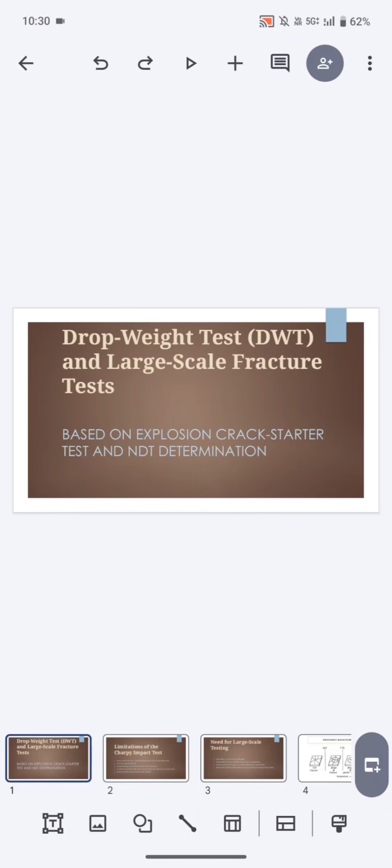The basic need for large specimens resulted from the inability to produce fracture in small laboratory specimens at stresses below the gross yield stress, whereas brittle fractures in ship structures occur at service temperature at elastic stress levels.